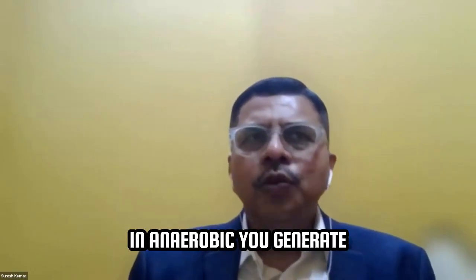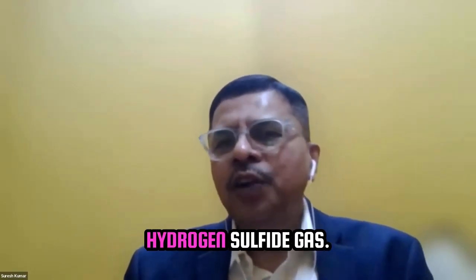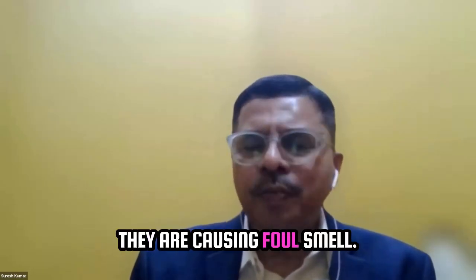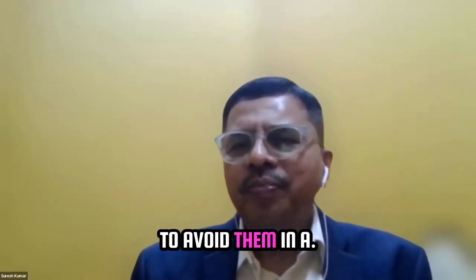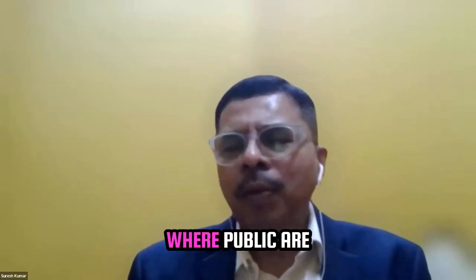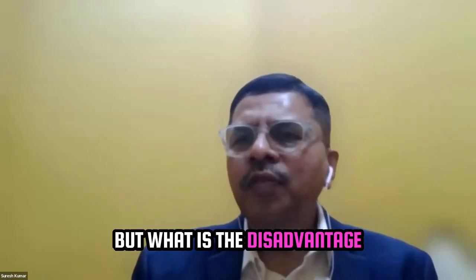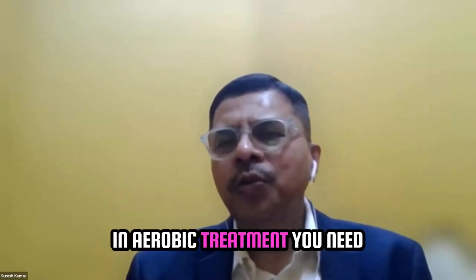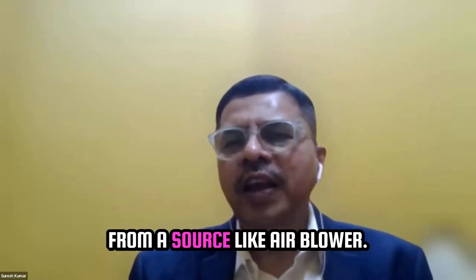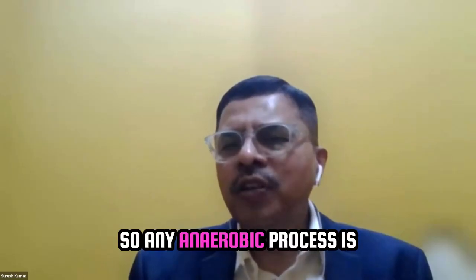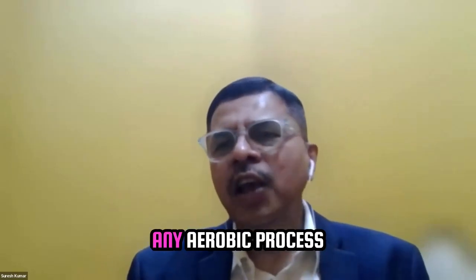Now, in anaerobic, you generate methane gas, hydrogen sulfide gas. Both of these cause foul, obnoxious smell. So for this reason, we try to avoid them, especially in residential areas or where the public are going to be there. We try to avoid anaerobic treatment. But what is the disadvantage of using aerobic treatment? In aerobic treatment, you need to give external air from a source like an air blower. And air blowers consume a lot of energy. So any anaerobic process is energy free. Any aerobic process is energy intensive.